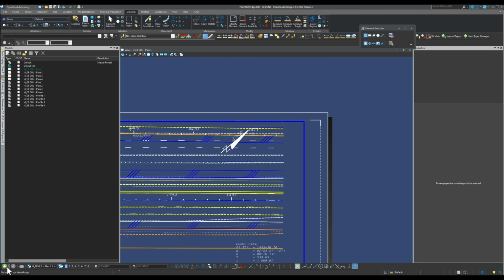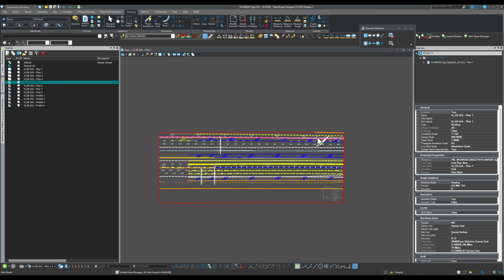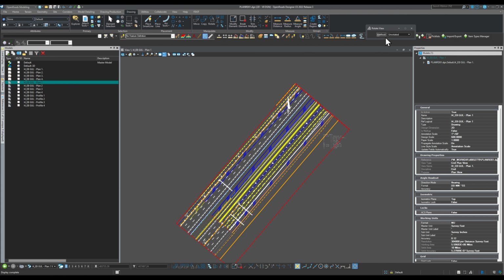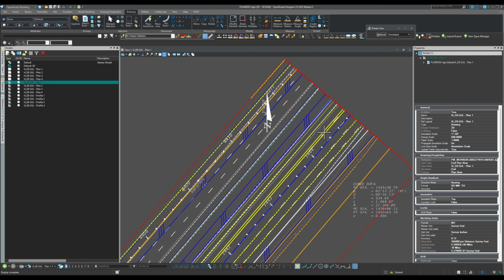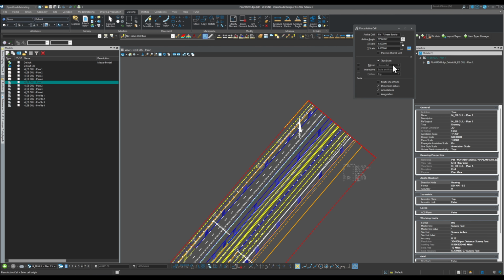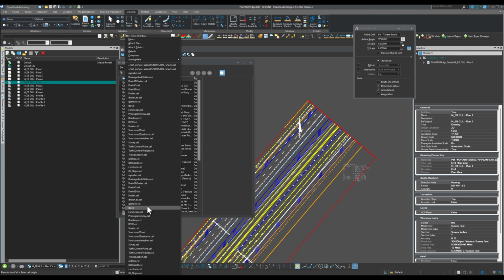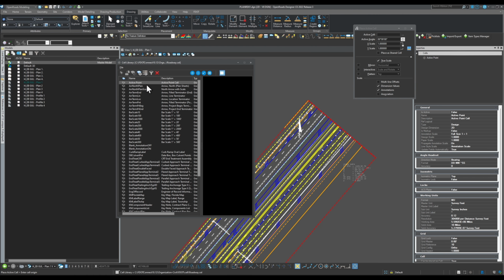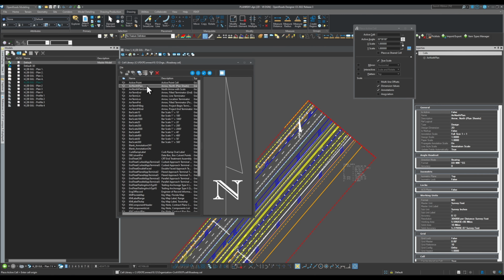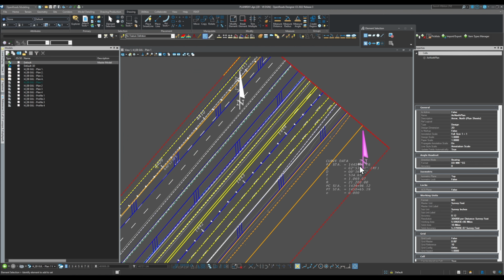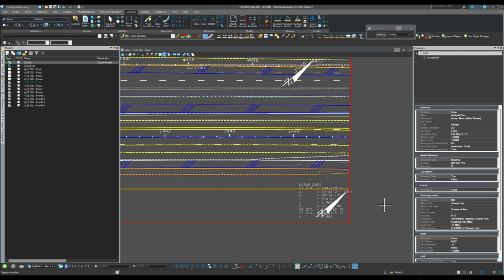So let's close this. Oh yeah, and let me just, if anybody wanted to get the arrows too, because I see a lot of people, they put the arrows in a default model. Let me show you how you can actually put them in a plan. You can do this dynamic, unrotated. The first thing you need to do is unrotate it, as you can see, because the cell is going to come straight up north, and then go to your cell and go find whatever your arrow is. It depends on your workspace, right? Yeah, let's say I want to do this one, right? Pop, click on it, and then drop it wherever you want to drop it. Make sure it's unrotated now. Let's come here and let's do 2-point, and now let's rotate it how we want it to show in a plan. Ta-da!